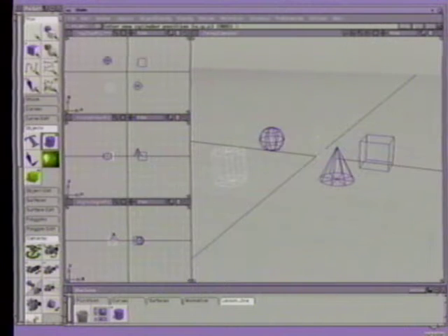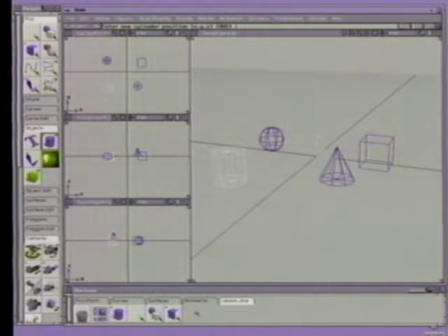In the tool palette, scroll up to the Pick section. Use the middle mouse button to find the tools. Drag the Pick Nothing, Pick Object, and the Pick Component tools down to the shelf. You'll use these tools later in the lesson, so you can keep them on the shelf for easy access.